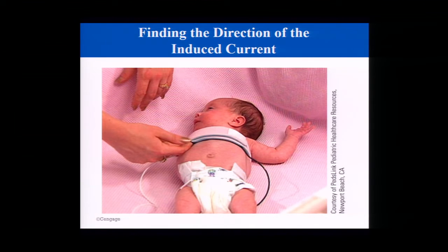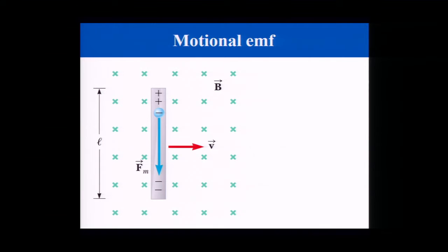The other application for this, think of my loop, okay? If I have a current that's running around in a loop, and I take a car, which is a big iron object, and I drive it across a loop of wire, the loop of wire is going to get a change in its magnetic field, which is going to cause a change in the current, which tells the traffic signal that I've got a car parked at the stoplight. So you've got induction rings out at intersections to help give a signal to change the car light. So that's one of those practical applications.